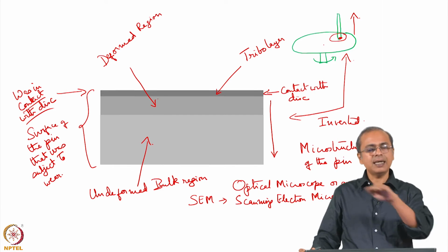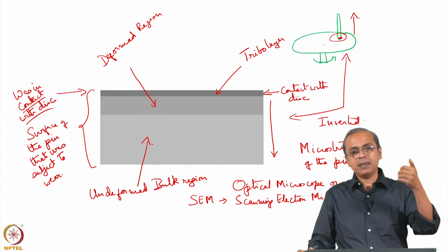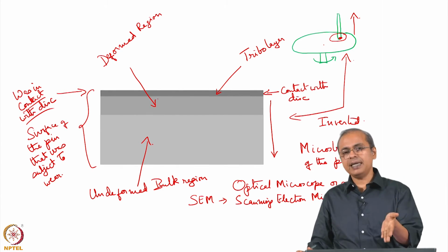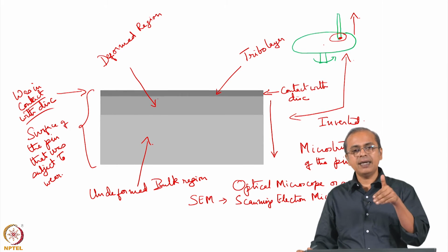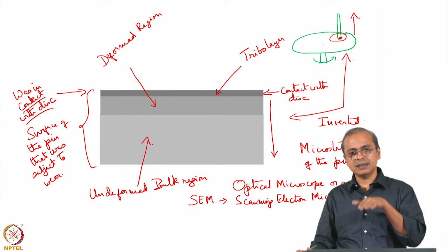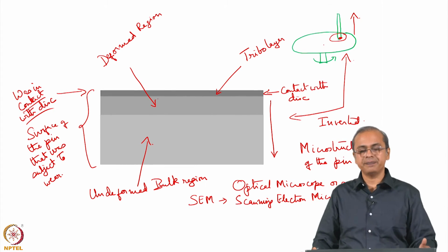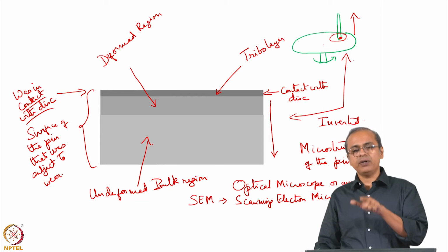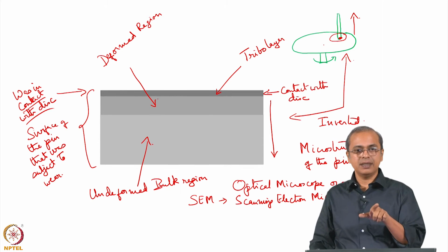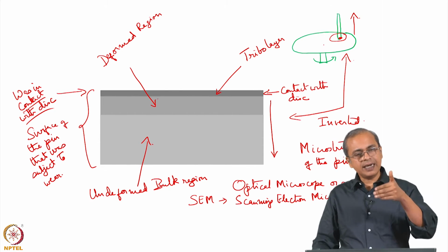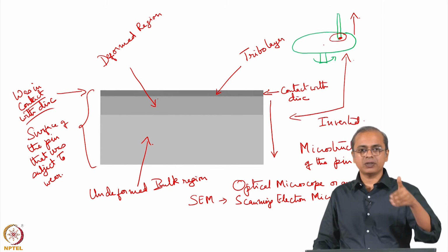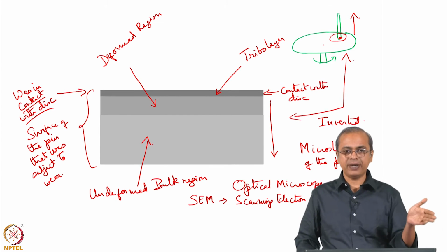It is a very thin layer, but it is a very continuous layer, and it prevents oxygen from penetrating into that sample and oxidizing the steel underneath it. So, that is how this stainless steel remains as stainless steel. Typically, if you take stainless steel and keep scratching it, then steadily the interior of that surface will keep getting oxidized, and then eventually the whole sample fails.